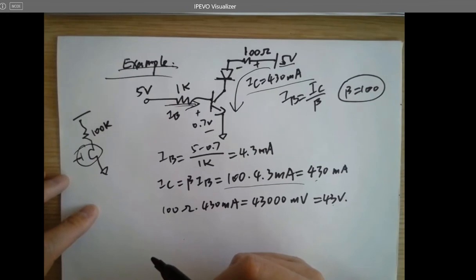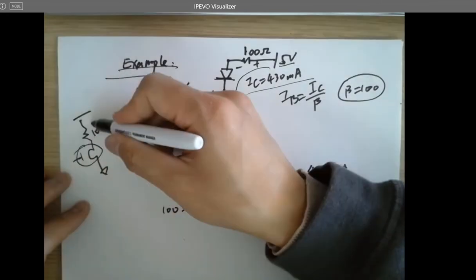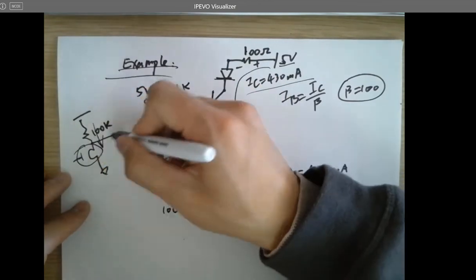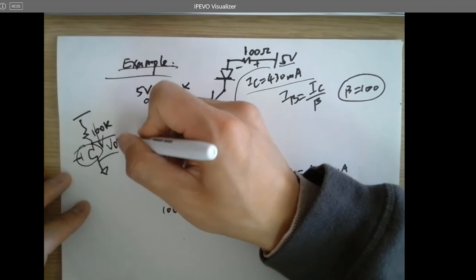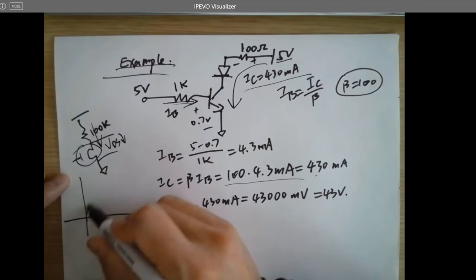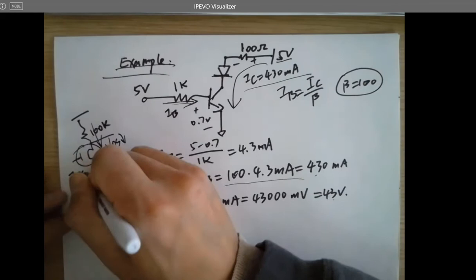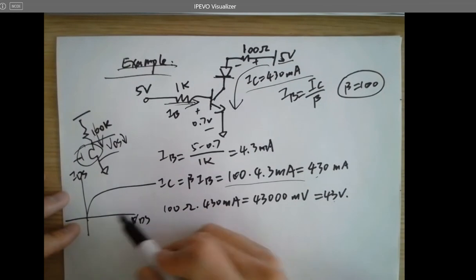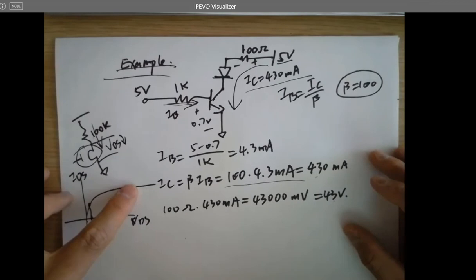It's probably in the linear region because the current will be limited. So we will have a smaller VDS. VDS will decrease. When VDS is too small, it's going to be here, not here.